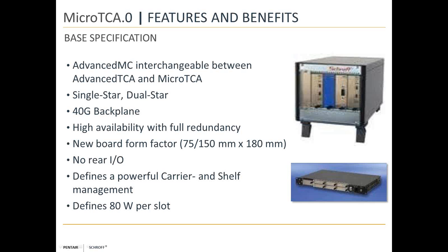For MicroTCA, however, a new module is developed in the Advanced MC form factor, and that new module is the MCH, or MicroTCA carrier hub, which performs both the carrier management and the fabric functionality.